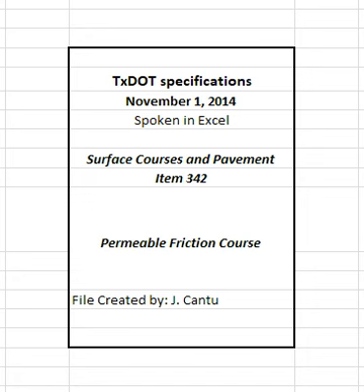4.4.2.2.5 Testing the trial batch. Within 1 full working day, the engineer will sample and test the trial batch to ensure that the mixture meets the requirements in Table 5. The engineer will have the option to perform the following tests on the trial batch. Tex-235-F, to verify that drain down meets the requirements shown in Table 4. Tex-530-C, to retain and use for comparison purposes during production, and Tex-245-F, to verify the Cantabro loss meets the requirement shown in Table 4.